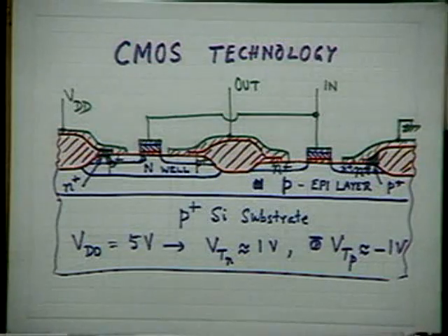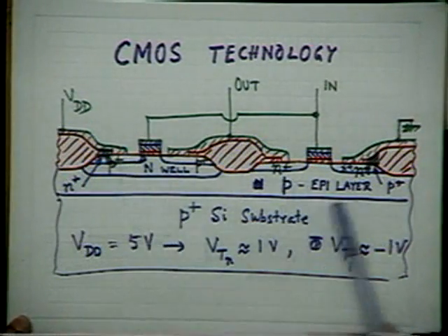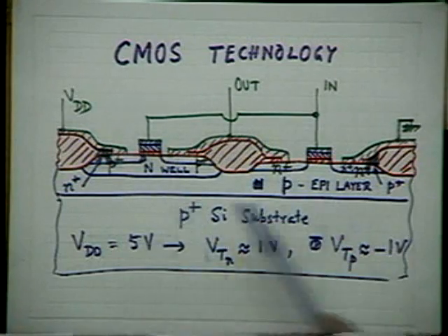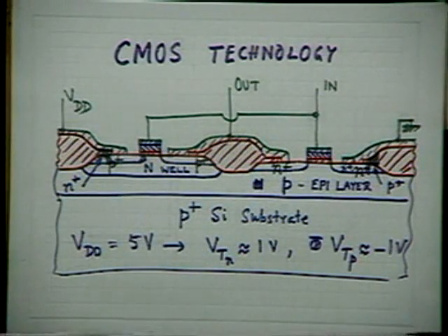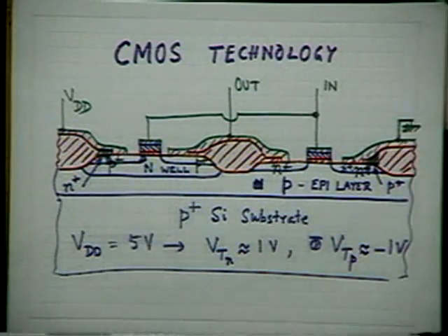And once this voltage rises above that so-called forward blocking voltage for this PNPN parasitic structure in the CMOS, then it will turn on. That is, between this point and this point, we have a short circuit, practically a short circuit. And the inverter will not work. Unless you switch it off and once switch it on, it will. So that is a very severe problem in CMOS circuits.